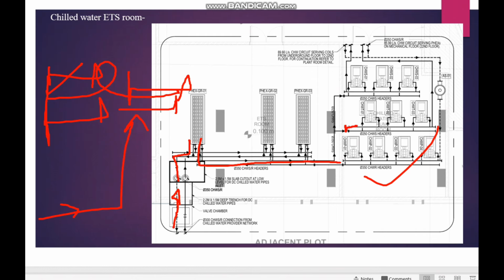So normally this pump spacing, 1 meter by 2 meter, I will provide for all the pumps except vertical inline pumps. Then on the front side provide 1 meter, and this side also provide a minimum of 1 meter spacing, and 1 meter spacing for the wall connection. Okay, front side 1 meter minimum we need for the strainer, valves and other connections. Like this, for all the pumps you have to provide when you go for the space allocation.